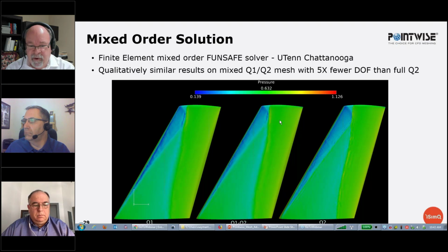You need linear scalability with mesh size. This is a combination of the numerics that's inside the solver, something like additive correction multigrid, but also you need to perhaps increase the number of CPUs. You need parallel processing to work well with it, so you can manage your overall CPU time.